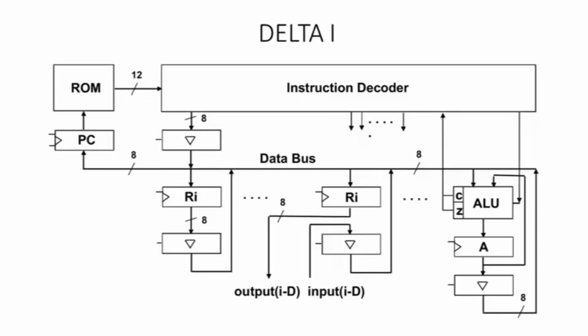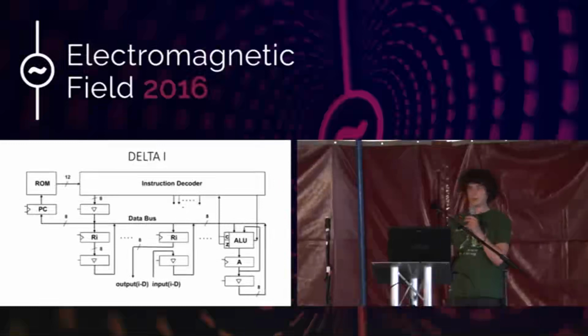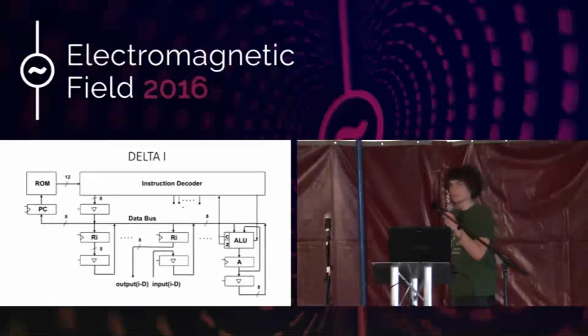And to make this ROM, you give it a bunch of inputs, which we call address lines. And we say when the counter is at that value, then it will put this value on the address lines. And then making a truth table, you can say, okay, so when this value is on the input lines, then we should show this instruction on the output. And then similarly to what we did before, you can make a logic circuit that does that. That will always show this value at the output when you give a certain address at the input. And it's a lot more complicated than what we did before. But like I said, you have systematic methods to do this. And these days, we usually just let a computer do it.